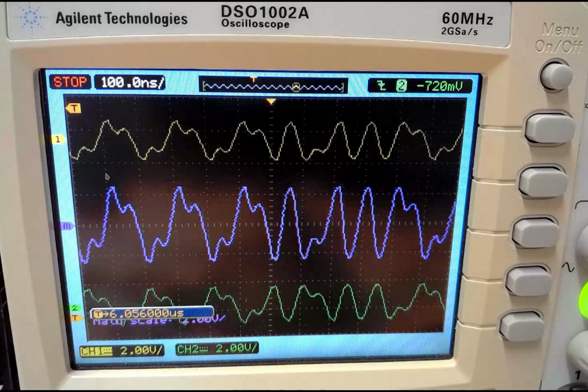So here you can see it's gone from a 1 to a 0, so that encodes a logical 0. And from here it goes from a 0 to 1, so that encodes a logical 1. So here we've got an example of how you transmit 2 zeros. Remember, there's a sample point here, so that's a 0. So it has to go up so that it can come back down again to transmit the second 0. Every sample point here. So again, this is a 0 to 1, so that is a 1 being transmitted at that point. So to transmit another 1, it has to go back down again so that it can go up for the next sample point at the next point in the signal.